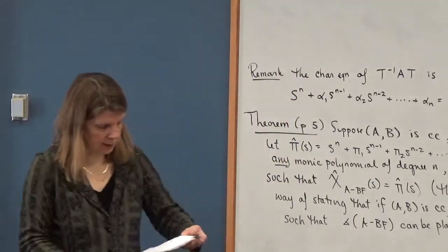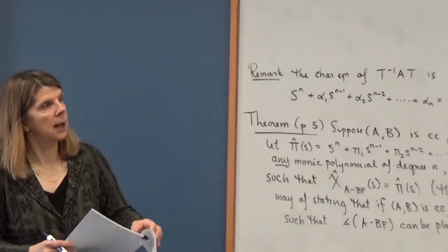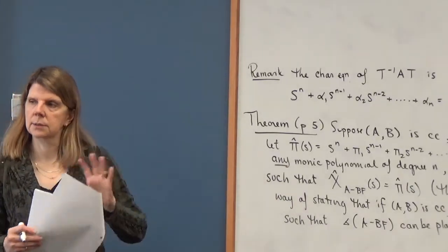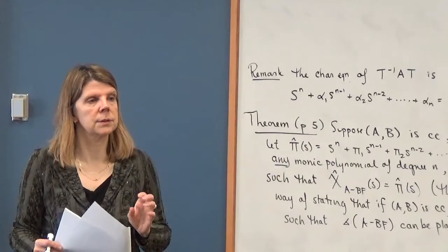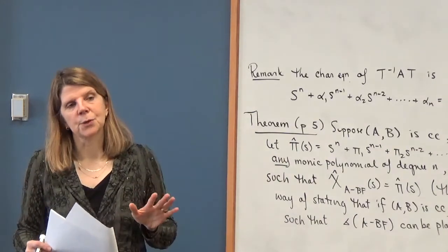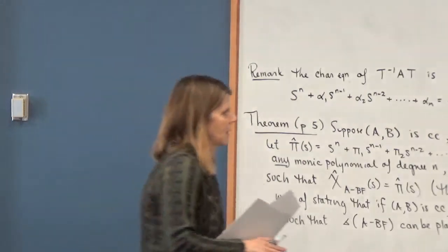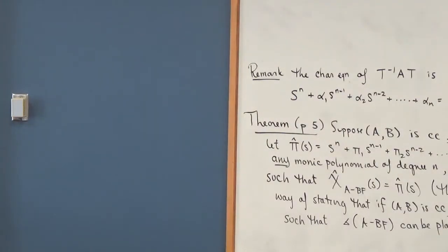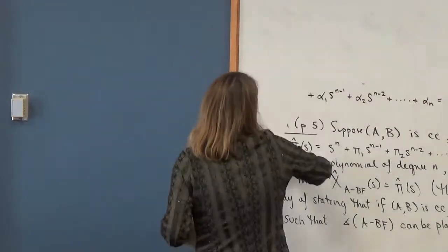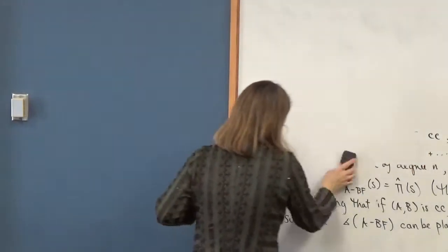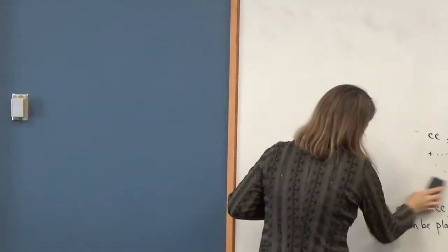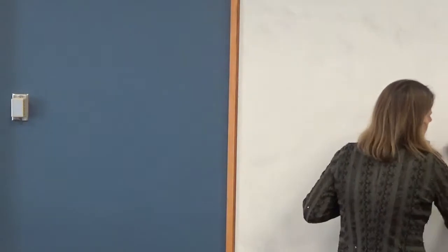All right, so the reason to do this observer design now is because the observer design process really mirrors the controller design process, sort of like observability tests mirror controllability tests. Let's introduce what this all means. It comes back to a point that I've said a few times. We're assuming that we can measure the state directly, and we can feed that back through the feedback gain matrix.